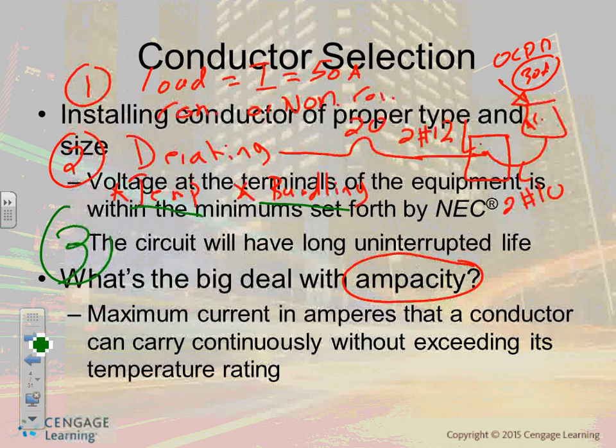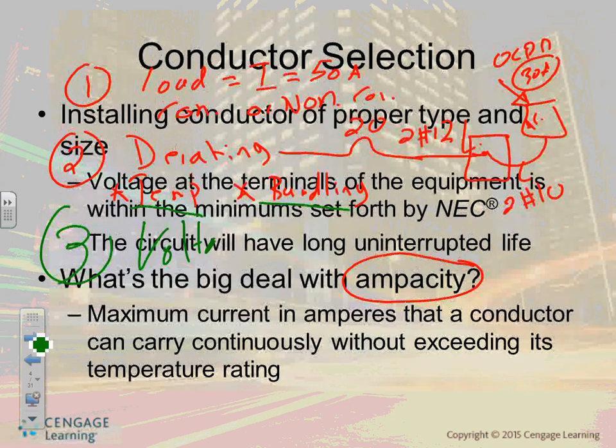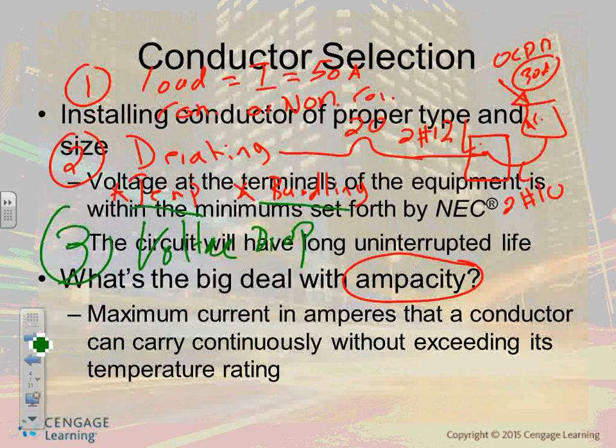Did I spell it right? Bundling. Okay? The last thing that a lot of people forget, guys, I want you to put it in your mind all the time. Voltage drop. So you have to take into consideration voltage drop. That's why when you size your feeders, if you're right on the border, you can go up or down, go up. Why? Voltage drop. Always take this into account.